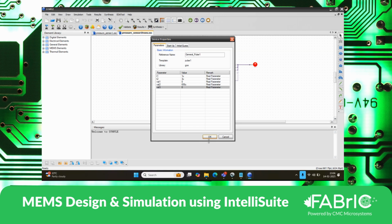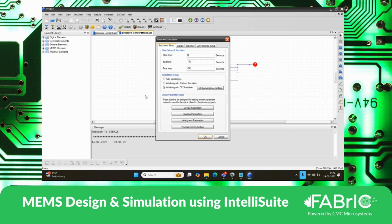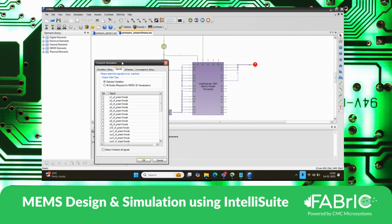So that is what we are trying to do, and this is a time based signal that we are giving. Hence we perform a transient based simulation where the end time of the simulation is 10 microsecond and the time step for it is 20 nanoseconds, and the signals that we want is what we can check.